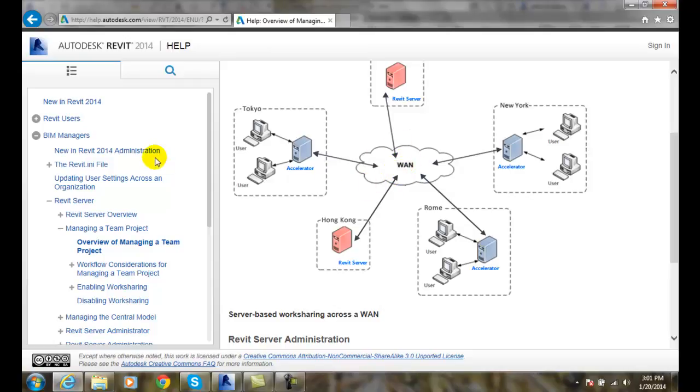And so then when this person wants to access it, they actually go and get a localized copy. This server grabs the information off the central server and gets a localized copy, and they make changes, and it updates the changes to the master central server. The reason why we make a copy at the local level is because to copy the entire project over the WAN, fiber optic, or internet lines is very slow. So we'll put a whole copy of it, and then just the small changes that have to be made are changed to it, and then they are changed to the central server.